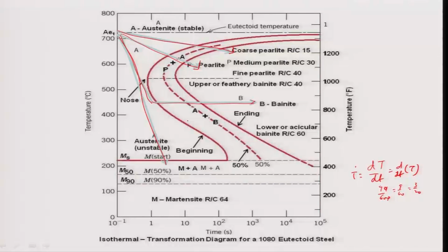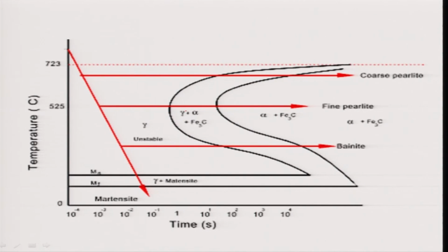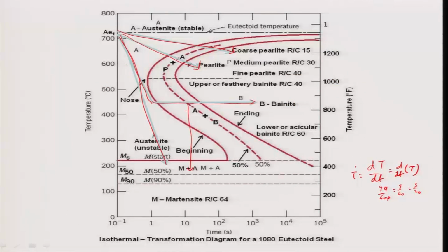You can produce a mixture. You can form a certain fraction of martensite: quench, it will form martensite, the rest austenite. Suppose you cool it like this, hold up to this temperature and quench, what will happen? You will have a bainite plus martensite mixture, correct. Okay. So, as you see here, the cooling rate is very high for martensite transformation. That means you have to quench very fast, and if you quench the sample, you will form thermal stress, and thermal stress will lead to formation of cracks, the sample will break.